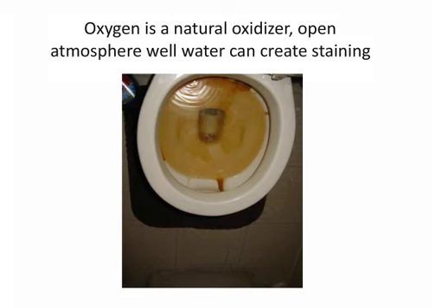Now, this doesn't mean you can't use it through the heat pump. It just means you need to monitor it after that geothermal installation so that you'll know when you'll need to come in and flush out that heat exchanger and scrub it back down so you get good transfer. So this is not a deal killer, but you need to know this going in so that you can suggest what kind of maintenance levels they may need.